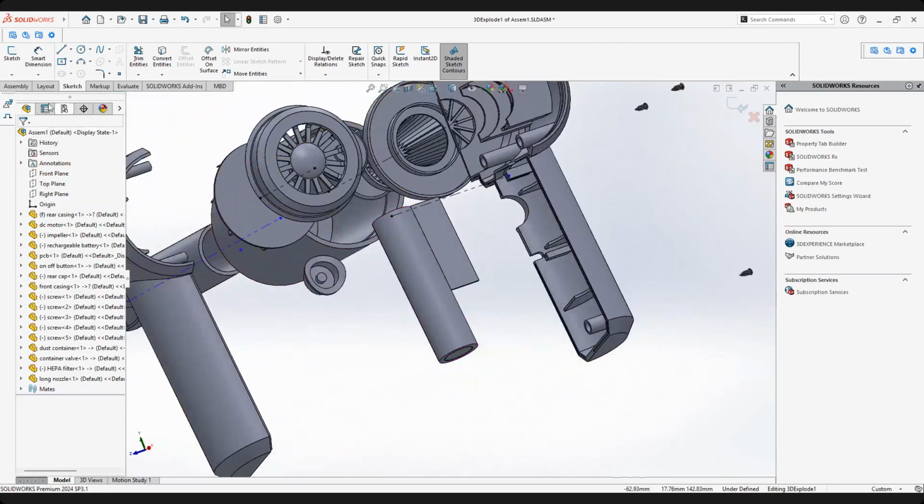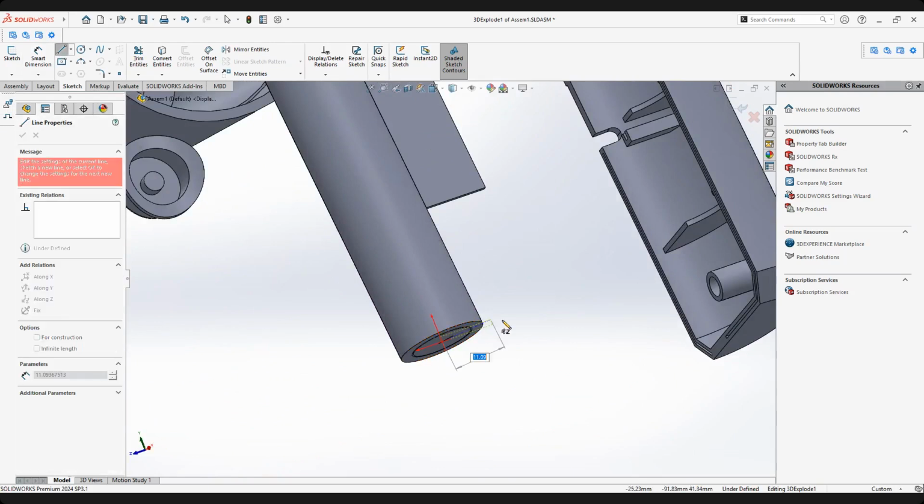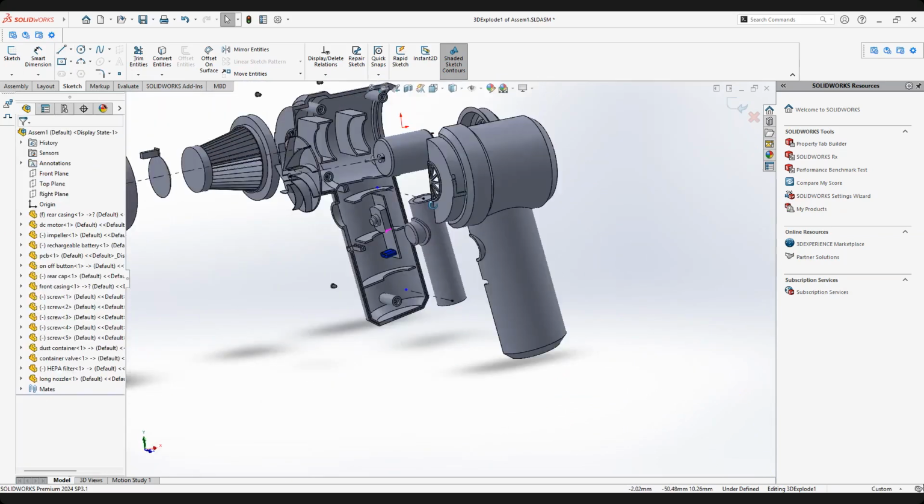Another jog line, not the root line, the second one. I can select the center point here. So I create the line first. Make sure it snaps at that center point. Then make sure your axis is YZ. You cannot go for XY, YZ, and it goes like this. So you have to do it manually like this. So this will be the path line for the battery to be mounted onto the casing.